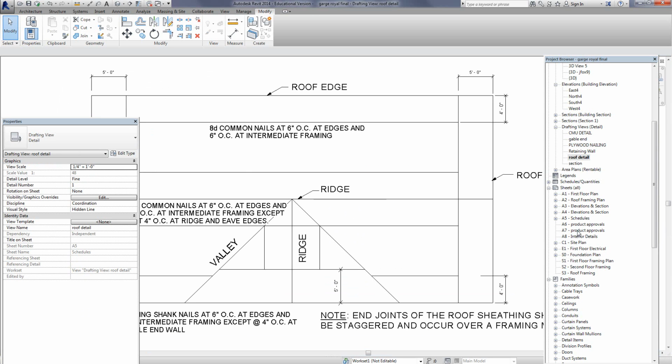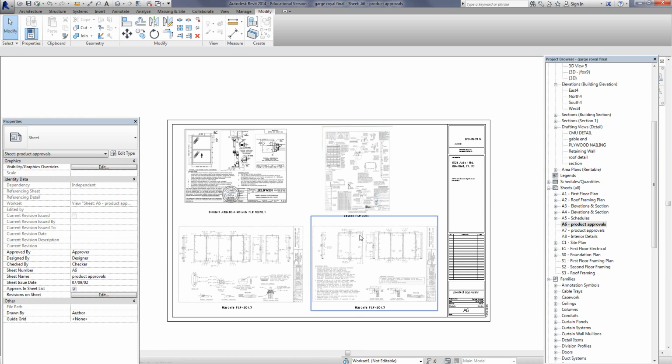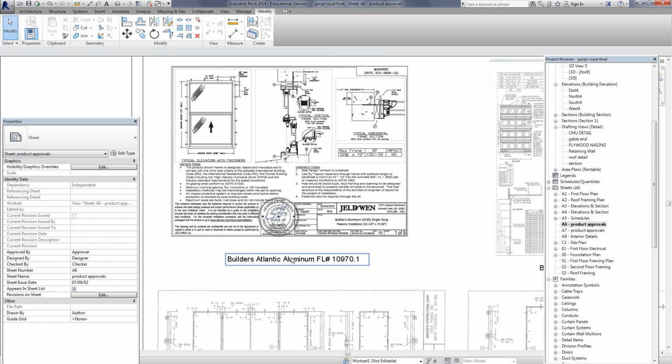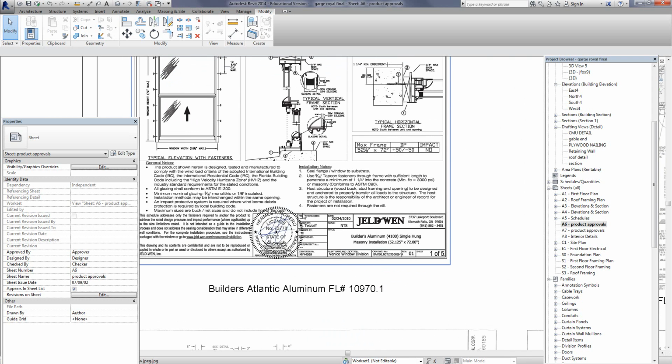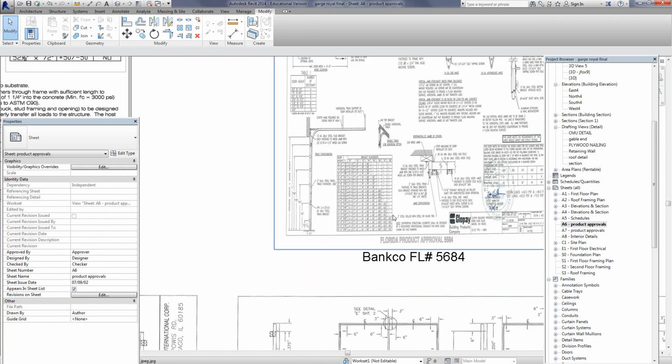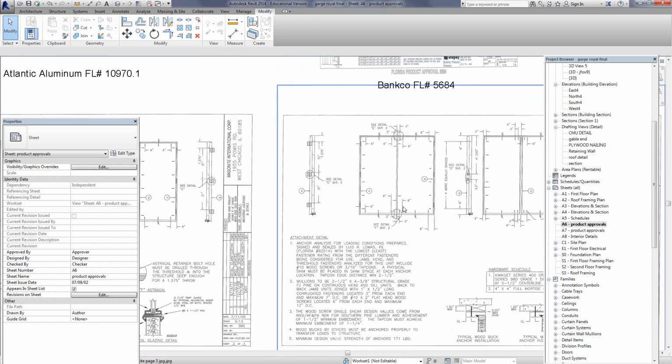Okay, so that again begins to show you guys, here's the product approvals. These are the different, as we went on the floridabuilding.org website, you can go through and get different product approvals. And as you can see here, the reason I want a product approval is to show that these products have been tested for the 2x4 being shot through them.